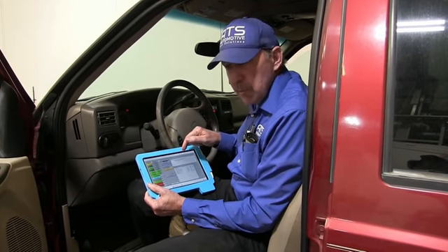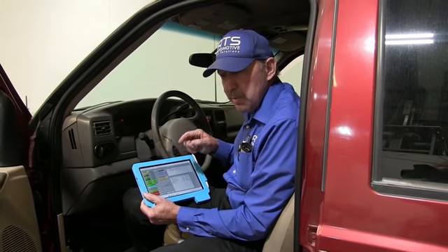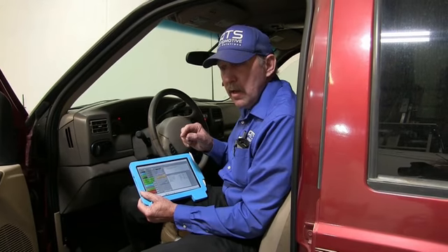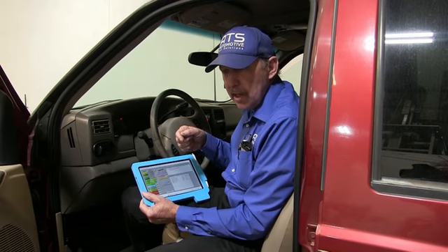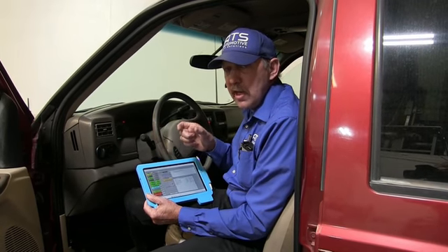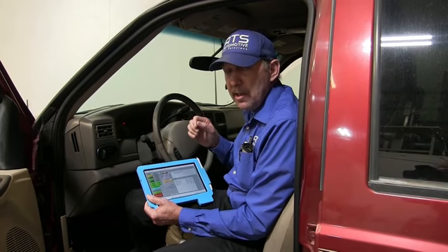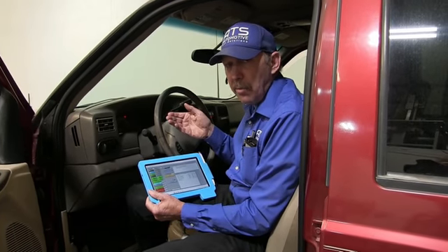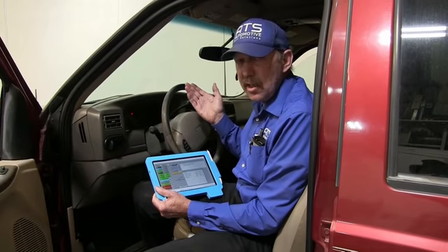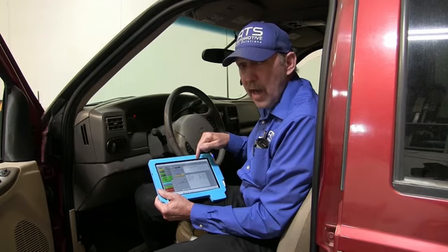But if the output speed sensor is breaking down, and I've seen this where the speed sensor is breaking down, the output speed sensor has a higher rotational count than the input speed sensor, and then it shows the tranny is slipping, so they cut injectors on the motor to try to limit the torque so they don't burn up the transmission. On more modern cars, they don't cut the injectors, they close the throttle blade on drive-by-wire. But this isn't that new a car, this has got a Bowden cable. So I'm worried about this code right now.